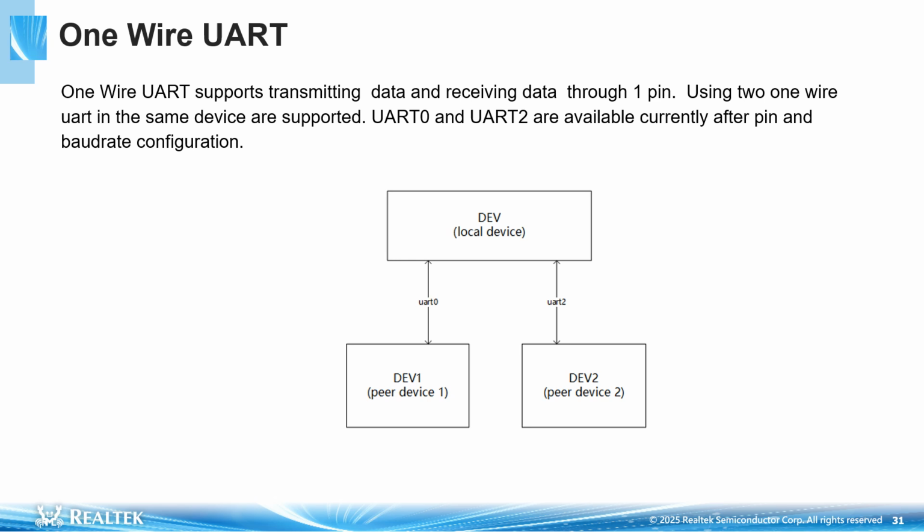Secondly, connect the GND, VCC, and UART data pins of the two devices. Thirdly, the baud rate should be configured the same as the other side. Currently, baud rate is configured as 115,200 through parameter app_cfg_const.data_UART_baud_rate.